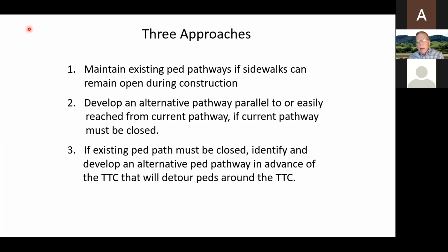If we can't do that, then we may need to develop some sort of a detour path, like maybe to the other side of the street, like that situation I showed you in New Orleans. There, both the sidewalk and the parking lane basically were occupied by construction-related activities or equipment or materials. So there we have to have maybe a more extensive detour route to take people to the other side of the street for a block or two, and then back to the original sidewalk section. So you have to consider which of these approaches applies to your particular job or activity.